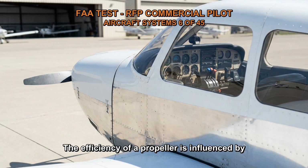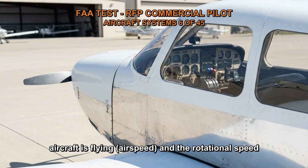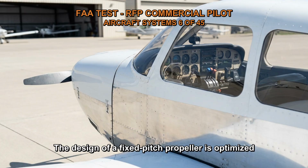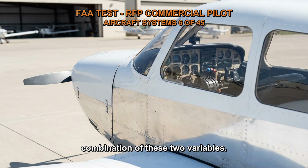The efficiency of a propeller is influenced by various factors, including the speed at which the aircraft is flying, airspeed, and the rotational speed of the propeller, RPM. The design of a fixed-pitch propeller is optimized to achieve its best efficiency at a particular combination of these two variables.